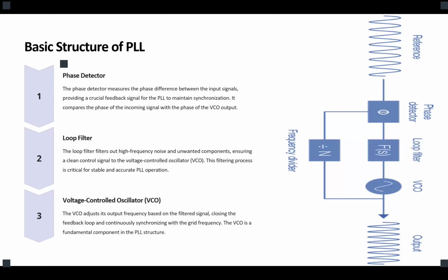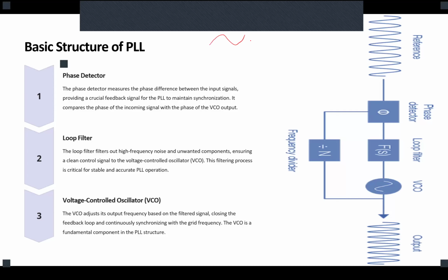See, this was the PWM in MATLAB. You had a reference and a triangle, and you compare these two with each other. Whenever the reference was higher than the triangle, you would ignite the switch. Correct? Now, before, you had a sine wave generator in your MATLAB system with a constant frequency.